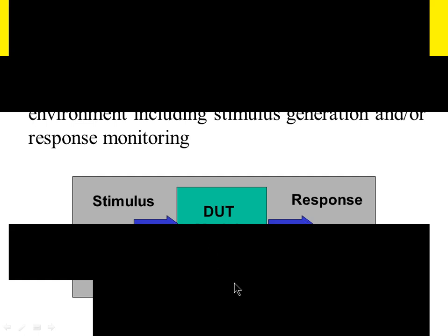In the test bench module, we apply stimulus or inputs to the design under test, which is the top level of the design. Based on the inputs given and the logic of the design, it will generate some response or outputs. At the test bench level, we monitor the inputs and the outputs. This generates a timing diagram for us, and we analyze it. If the outputs generated are correct as per the inputs and the logic given, we say that my design is functionally verified.